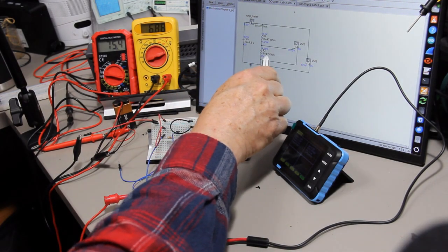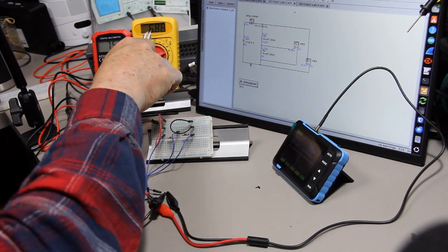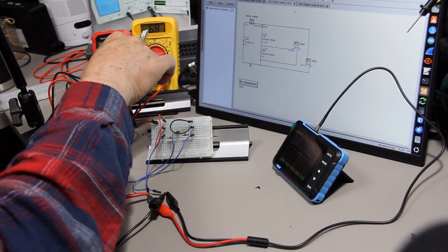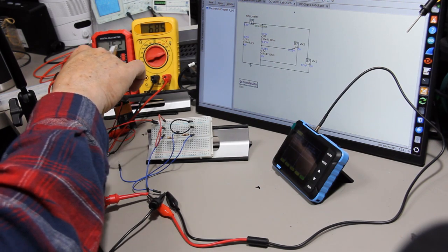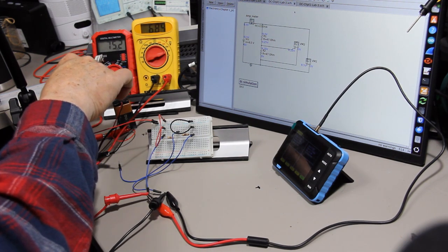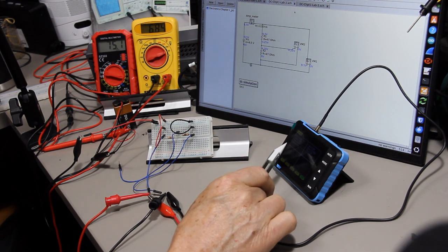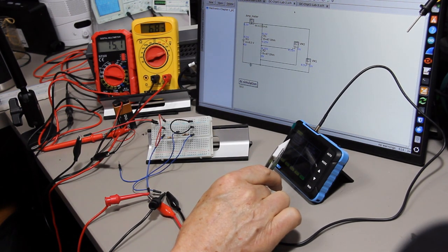So two resistors in series: resistance doubles, current drops by half, voltage splits right down the middle. Ohm's law called every number before we touched the wire. In the next video we go into parallel circuits. It's 4 resistors, 2 in series, 2 in parallel. The current splits, the math gets a little more interesting, and you're going to see why parallel circuits behave the exact opposite of series circuits.